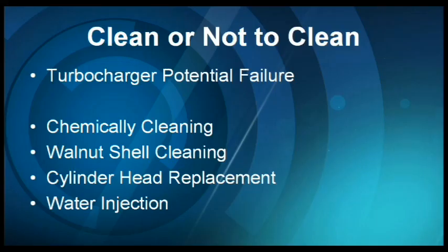I believe that water methanol injection is probably the future of some of these direct injected turbocharged engines that every manufacturer is utilizing. Only BMW at this time has chosen to use water injection as a viable way of keeping the back of the valves in the combustion chamber clean.